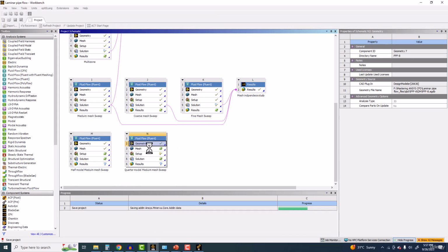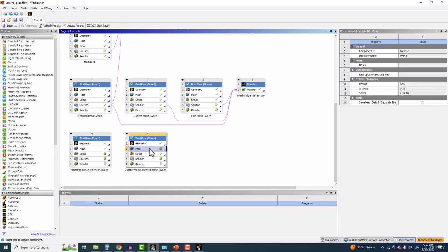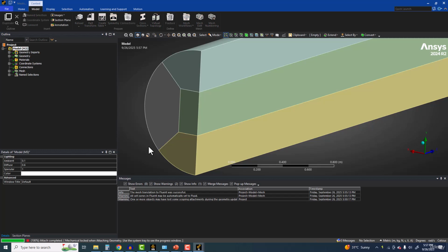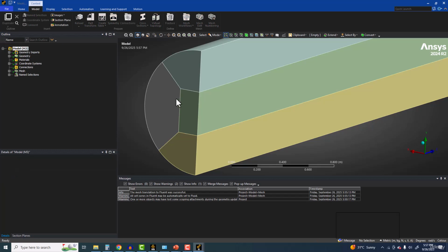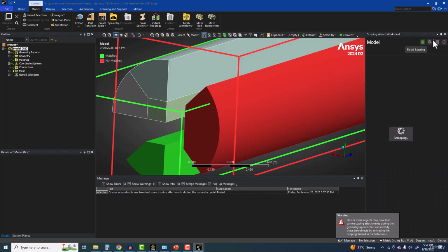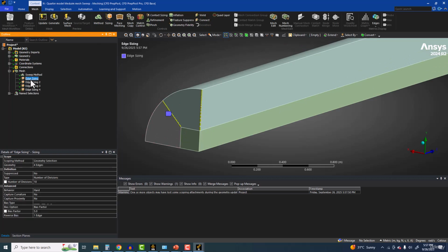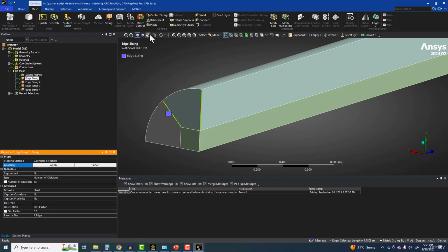This time be careful about where we have to half the size of the mesh. Definitely on the half geometry. Half geometry means that once you split with the help of the symmetry command, that geometry is no longer a full geometry. So now it's the half version. This time this will be extended to the second part as well. So these diagonal edges will go directly there. There's no exception here.